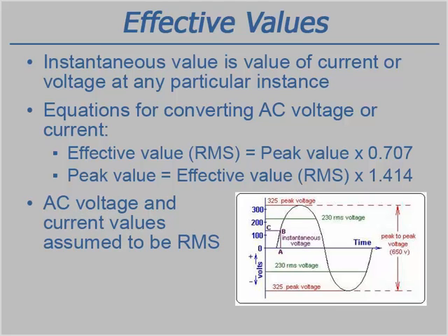Normally, when you encounter an AC voltage or current value, it will be stated as the effective or RMS value. Therefore, you may assume when no subscript is displayed for an AC voltage or current value that it is the RMS value.